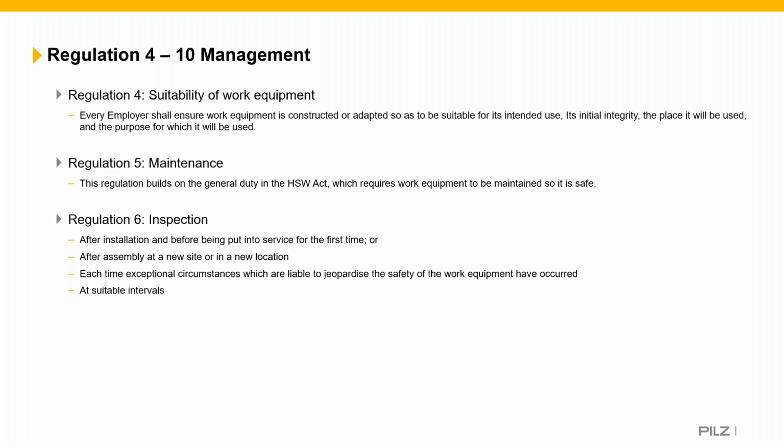We need to look at the potential risks from the work equipment, and what we need to look at from physical checks, functional checks, visual checks, and things like that. We need to inspect the safety related parts necessary for the safe operation. So overload warning devices, limit switches, functional tests may be necessary to check the safety related parts. So interlocks, protection devices, safety controls, etc., are all working as intended.